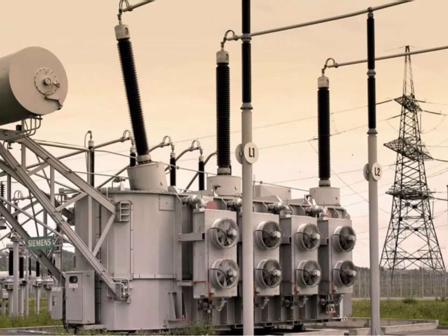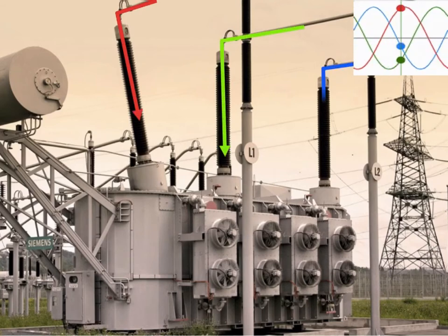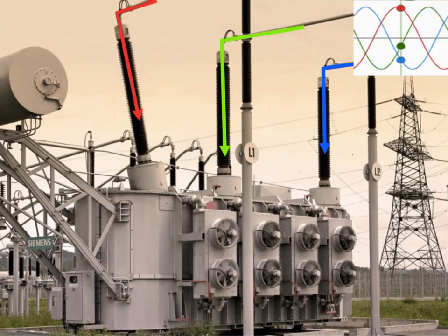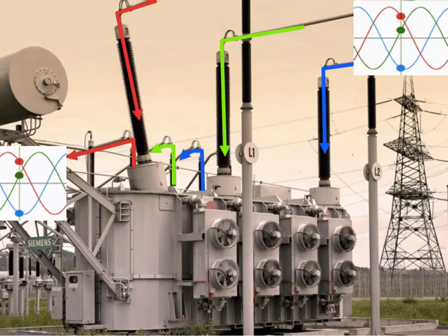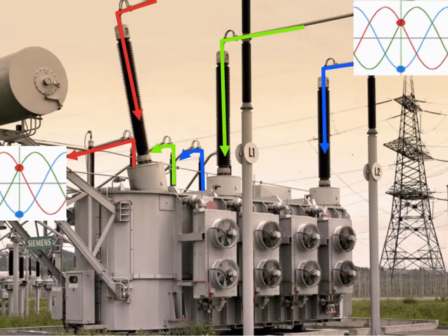The main purpose of power transformers in a system is to change voltage levels. That is, to convert the magnitude of the voltage either up or down depending on the requirements. For example, distribution utilities may want to take the high voltage transmission levels of 500, 230, 115 kV to voltage levels, say 25 kV, for ease of retail sale to customers. Or an independent power producer may want to step the generation voltage up to the level that could be connected